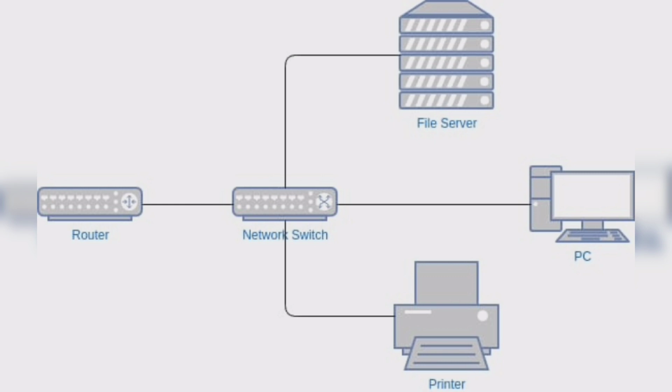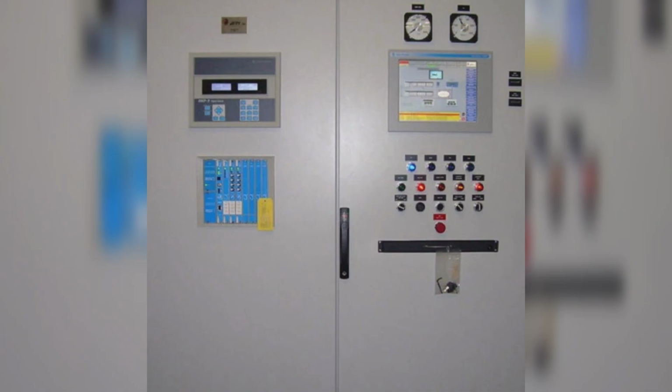Okay. Then the human machine interface, that is HMI. One of those devices is our human machine interface or HMI. The HMI can be mounted locally on the panel door or on a remote panel located closer to the machinery. The HMI is always mounted on the cabinet door. It will be visible to all the operators and engineers in the factory. The HMI can be a very dynamic tool in assisting the operator in controlling and monitoring mechanically. The PLC will also pass the signal over the network to the HMI for monitoring, and the HMI can send the signal to the PLC for controlling the machinery.